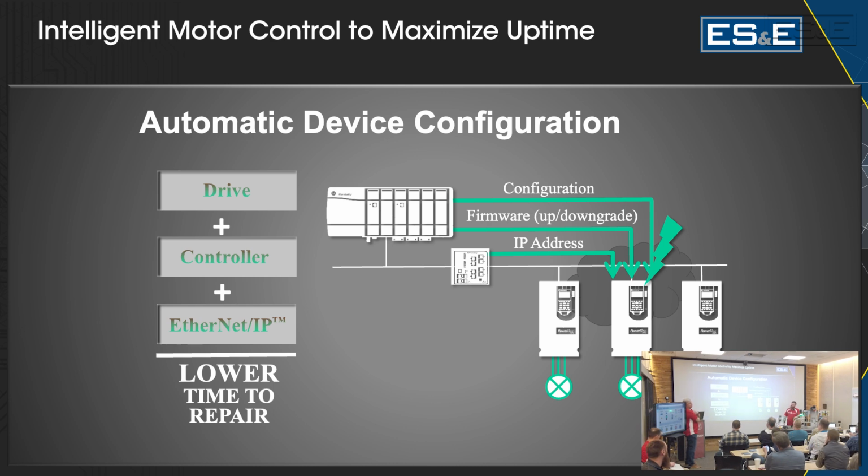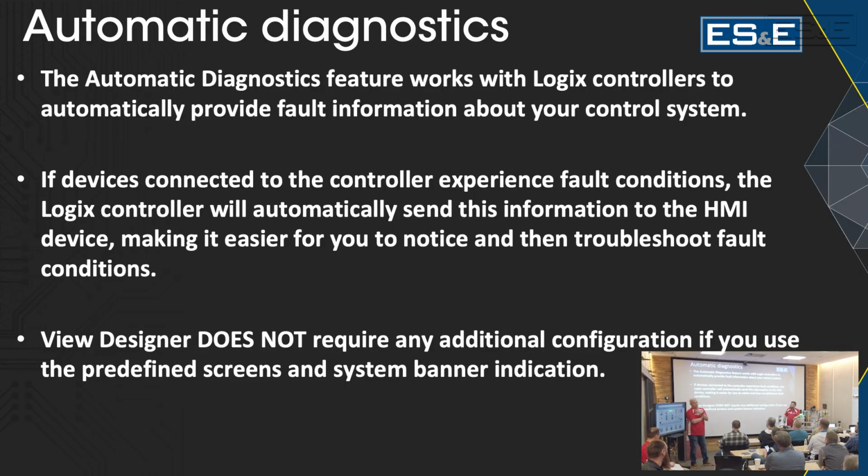Have you guys ever used the module status tag? When you've got any kind of device in your I/O tree, you'll know if the processor is actually talking to it, other than the caution sign on that device. There's a module status tag you can monitor. The magic number 9 is the value it will be if it is flashing the drive or the device.